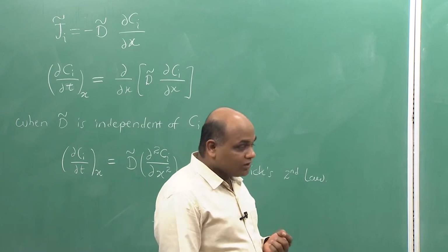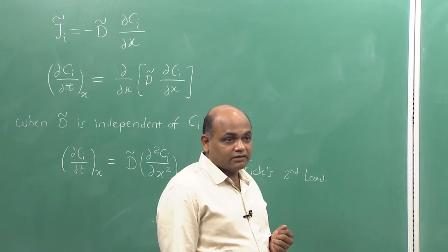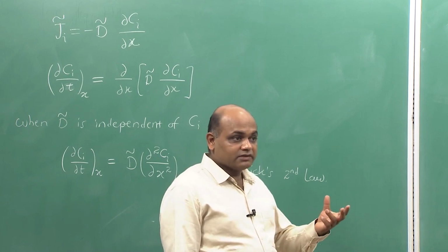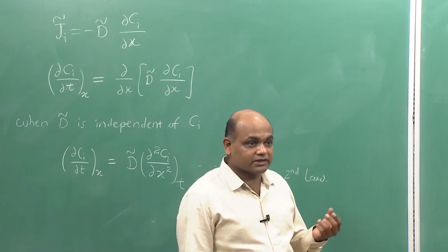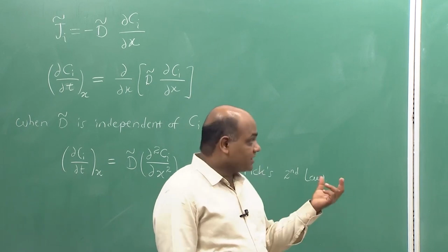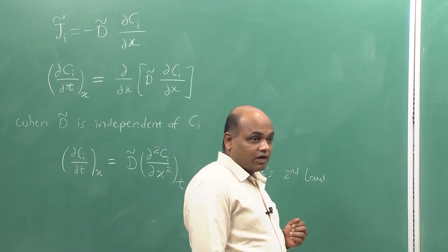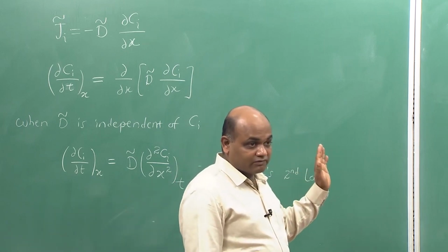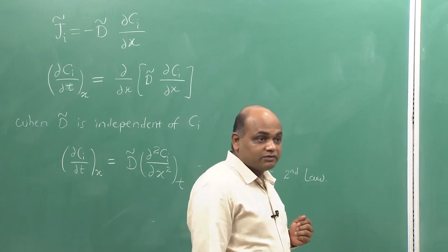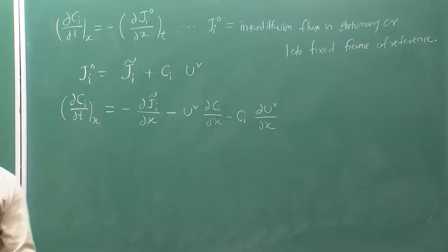If the partial molar volumes are functions of composition, then with diffusion there will be a change in volume, there will be net compression or expansion of the diffusion zone. And obviously, when there is an expansion or contraction, right. So, you can visualize along with the diffusive flow or the Fickian flux, there will also be the net mass flow because of the expansion or contraction. So, that you need to consider when you write the flux in lab fixed frame.